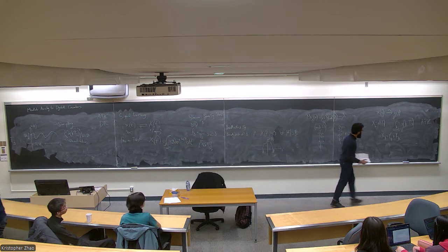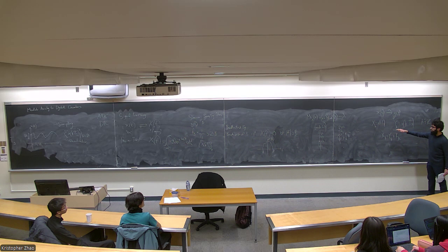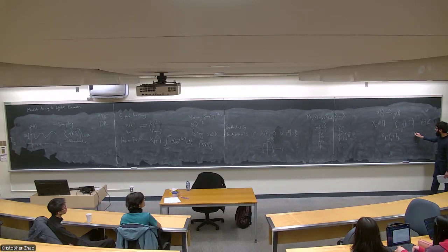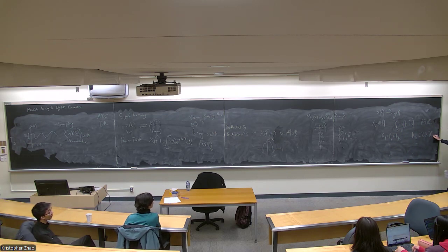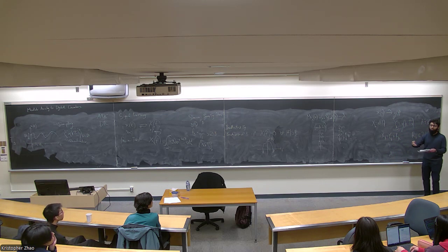So the first observation is that you can decompose the samples x sub k as y sub k plus r sub k, and by the fact that y is just a modulo of x, we also know that r sub k will always take values that are multiples of 2 lambda, because r is the difference between x and y, so it's equal to the difference between a value and the modulo operation applied to the value. This is an important property.